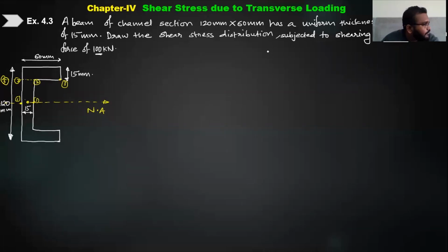39, Shashi Khatri. Yes, sir. Can you tell me how to go for inertia? We can divide this C into three parts, that is the central beam and the two flanges. Okay, we have taken this in three parts, 1, 2, and 3. So it will be 1 by 12 into 15 into 90 cube.